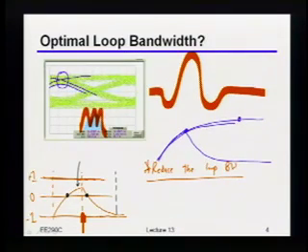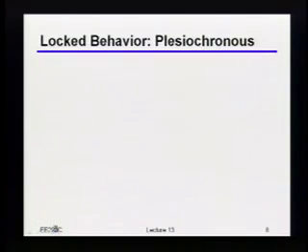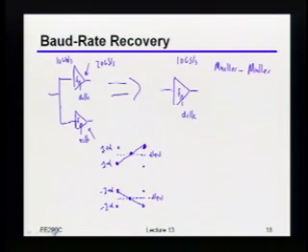So you could try and use that slope to recover some of the timing information, right? This is in fact much like the loop unrolled DFE system. It's just that if I'm not explicitly loop unrolling, the slope may be much lower. If I do a better job of equalization, then I may be better. But that's the basic idea, okay? Now this does, by the way, hint at why you're giving up something by doing this. And we can even go back to this picture right over here. So what is it that I'm giving up by doing things this way? Why is it that this may not necessarily give you the same performance as doing that 2x oversampled clock and data recovery?